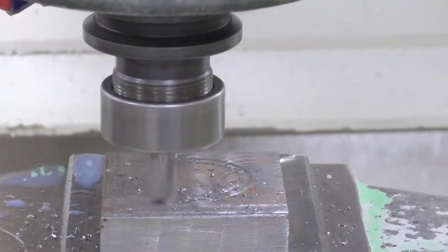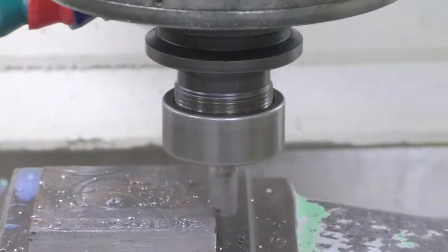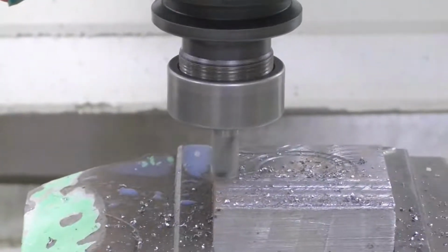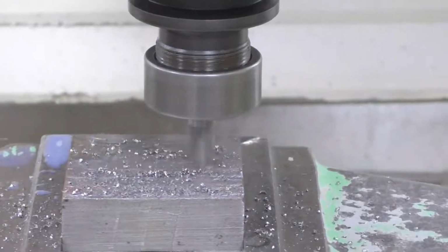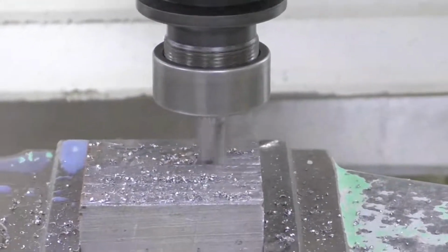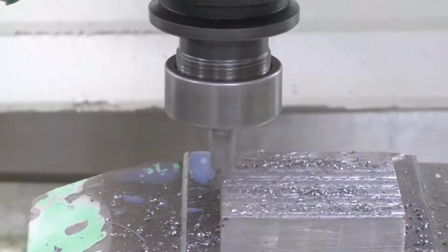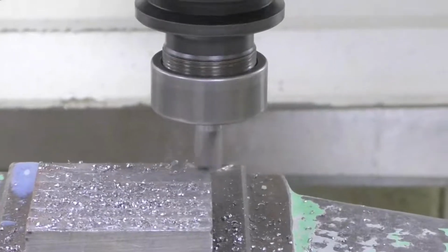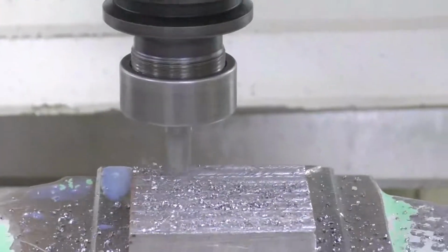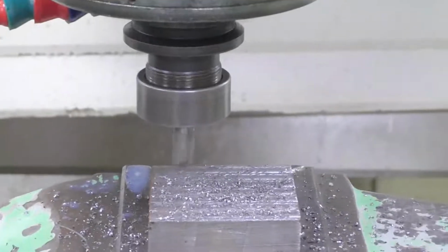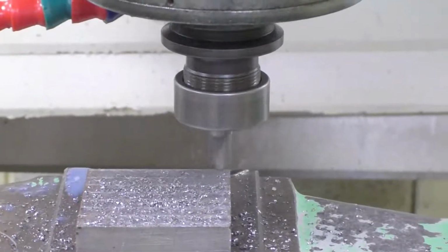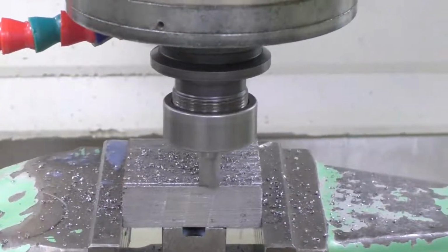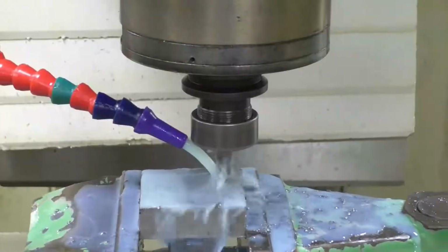So this is one of the zigzag facing cycles, I can say. As we have given the depth as 1 mm, till 1 mm it will be cutting in such a manner. So this is the depth it has taken, that is 0.2. You can see once it is completed, again now it will take another 0.2 depth. So this is 0.4 depth now in total, and now again 0.2 material is being cut.